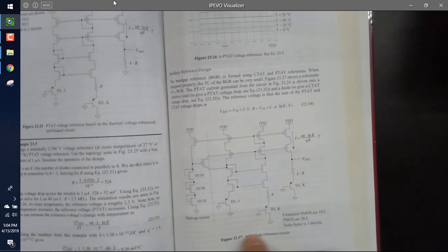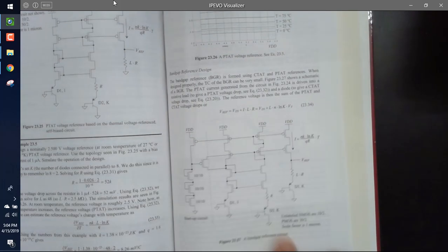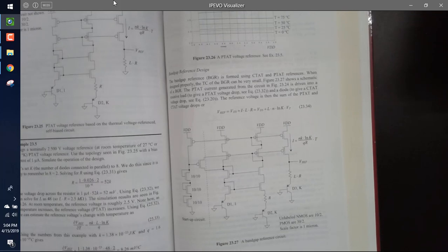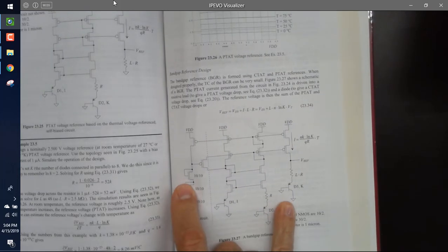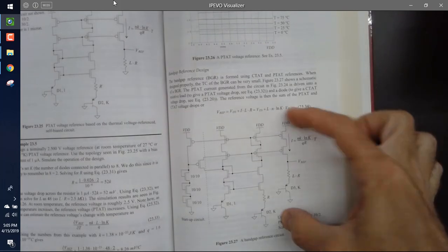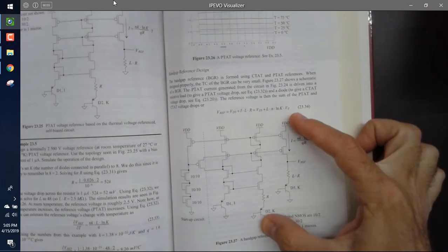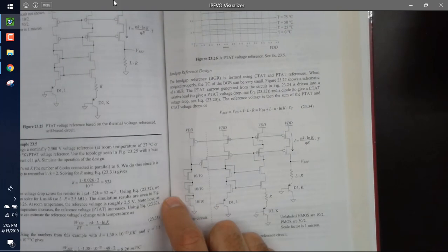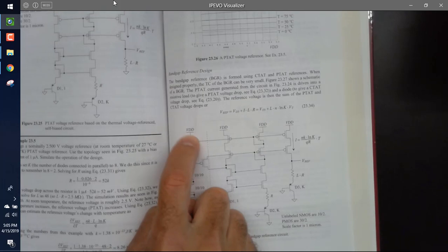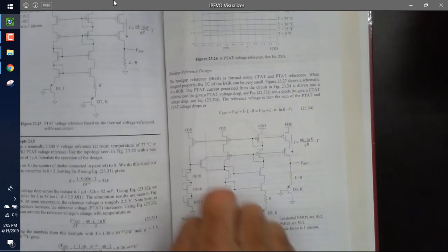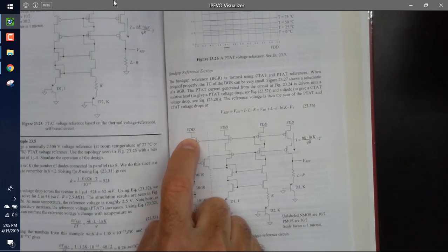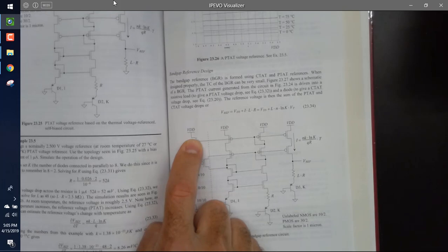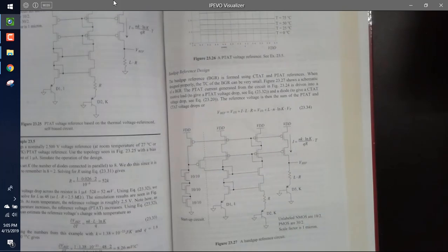And you should recognize, if you had 421, you should recognize this circuit from the circuit I had you lay out and use in your projects. Right? And you understand why now a little better, why if you change VDD, it doesn't influence the currents or the temperature behavior, because as long as you have a large enough VDD here, you're not going to affect the operation of the circuit. You should also be able to answer why the VGSs and the VSGs changing with temperature doesn't change the currents in the circuit. Right? Because if the temperature change in threshold voltage goes from 800 millivolts to 750, who cares? Doesn't influence the current mirror action.